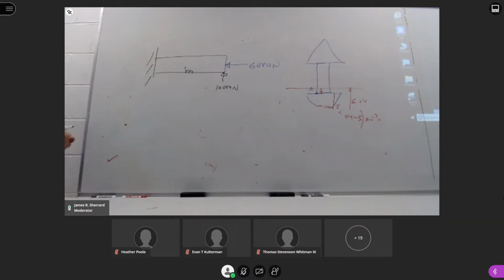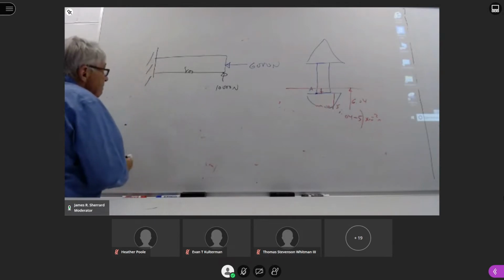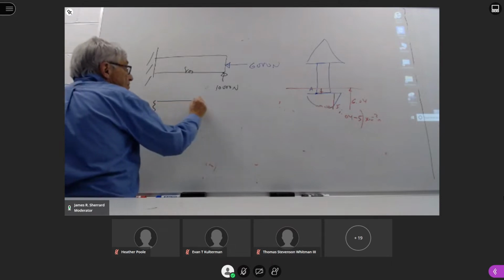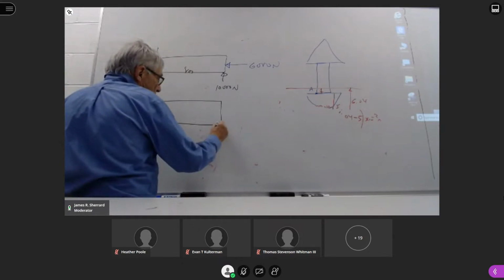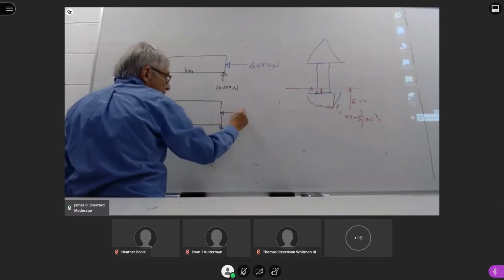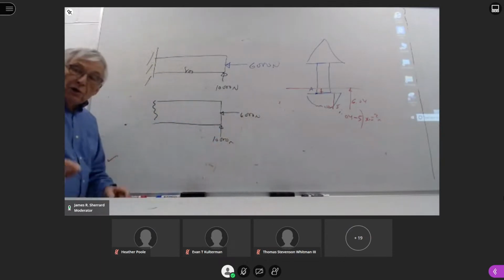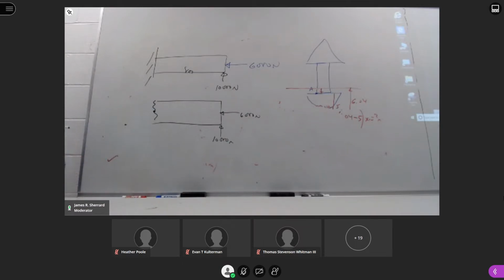And I'm going to ask you again to draw a complete free body diagram, and then I'm going to ask you to look at safety. All right. First thing we're going to do is our free body diagram. Sketch, remember, drawing any given forces, moments, torques, couples. We still have one attachment point. So that attachment point is the only place we can add forces, moments, torques, couples to put in equilibrium.